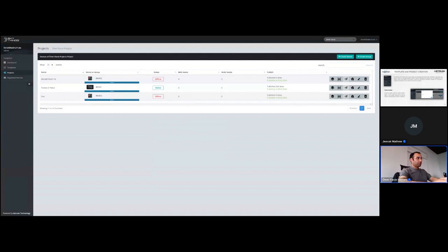I'm not sure if it will be the same for LKEP partners, but normally for every BMS control, for example KNX, Modbus, BACnet, SCS, every control, every group address, counts as one BMS node. Some devices, for example 8 and 10-inch panels, come to the end user with 500 BMS nodes.